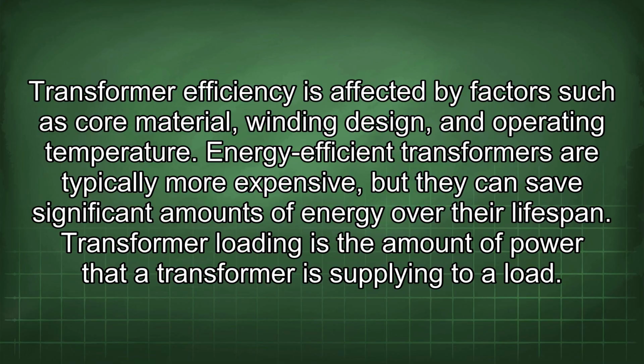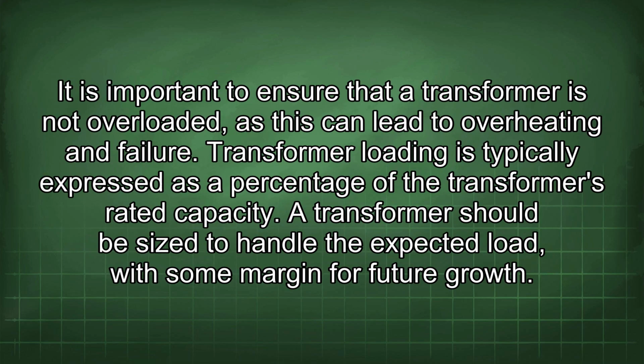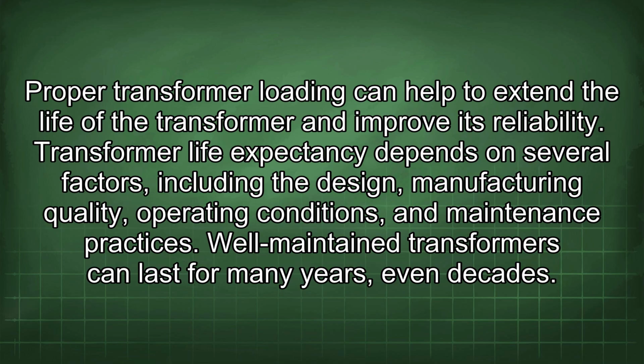Transformer loading is the amount of power that a transformer is supplying to a load. It is important to ensure that a transformer is not overloaded, as this can lead to overheating and failure. Transformer loading is typically expressed as a percentage of the transformer's rated capacity. A transformer should be sized to handle the expected load, with some margin for future growth. Proper transformer loading can help to extend the life of the transformer and improve its reliability.